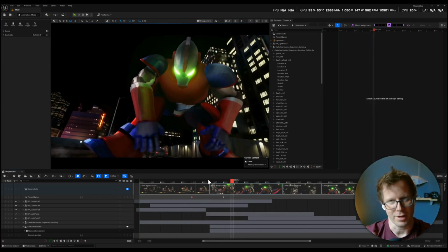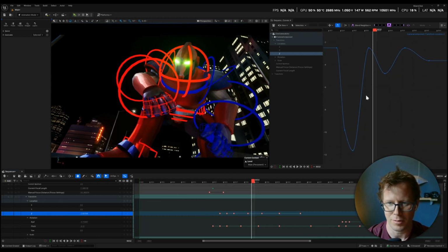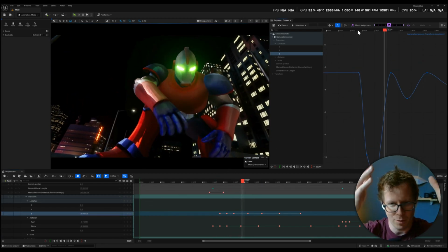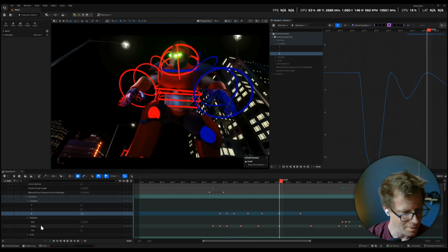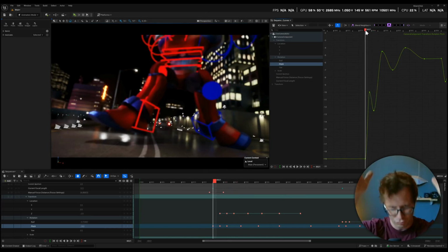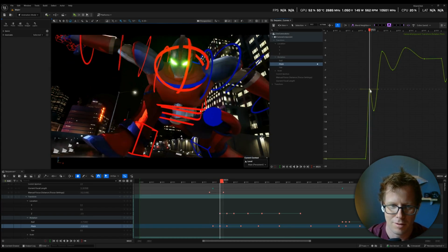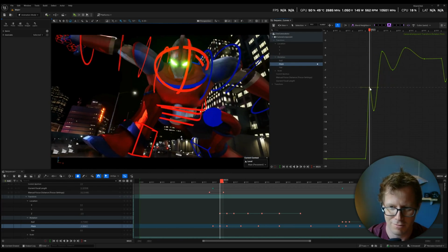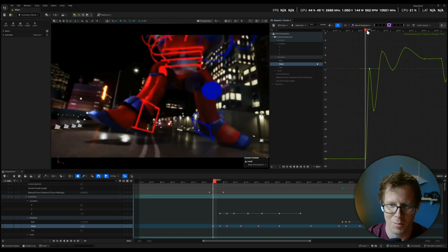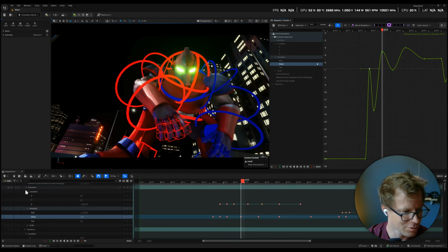So you add a little bit of camera shake to the camera. You can see that right here. This is the up and down motion of the camera, and then there's a little bit of pitch vibration that I added too. The camera goes up and down with the translate in Z, and it also has a little bit of pitch on it. So that's what you're seeing right here. And if you move those splines, you can see maybe I want that to be an even bigger impact. All easy stuff to do, just super fun.